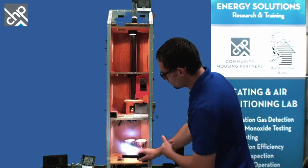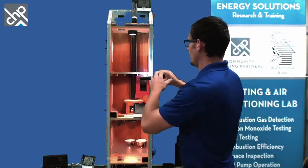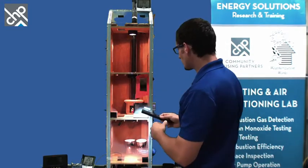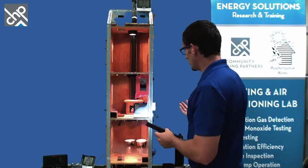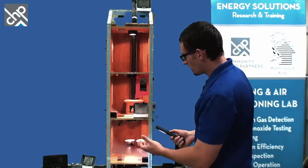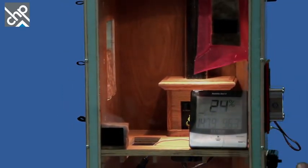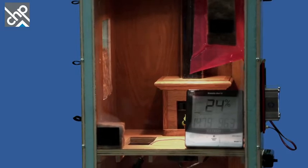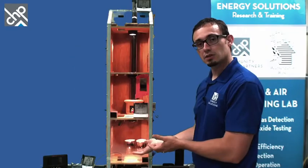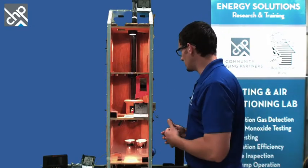We can watch this move down the wall. It's being removed from all these areas. That top floor that was starting to condense, no longer. So we're exhausting this moisture out. That's awesome. But one of the concerns that we have is when we kind of focus in on an issue like this, well, how we've tightened the house up. Now we've got this moisture problem. We can see it. It's a visible complaint. We need to deal with it. How are we going to deal with it? We're going to provide this ventilation.